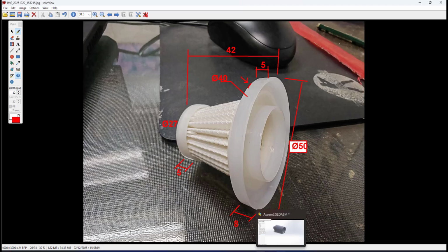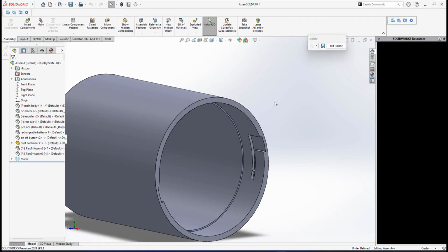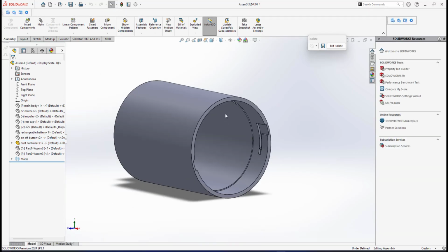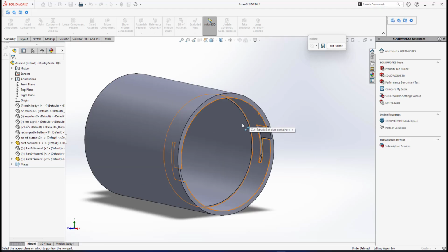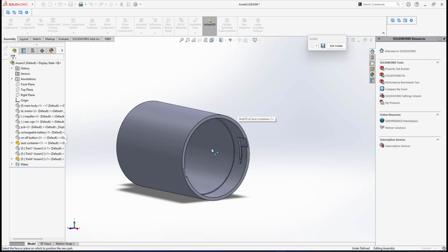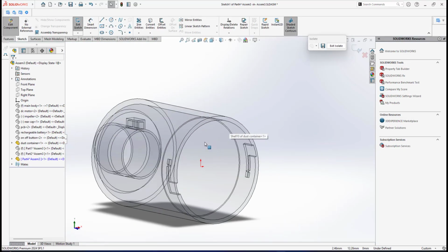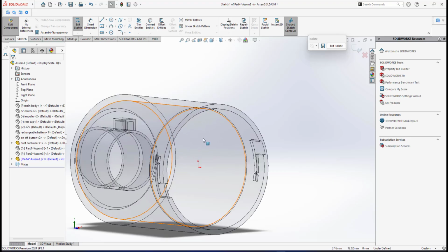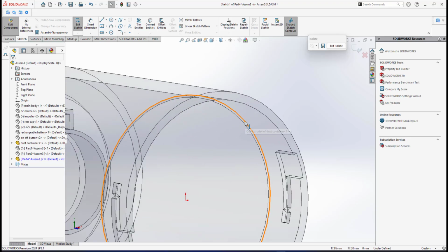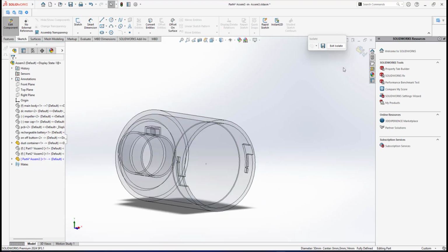Alright, so in SolidWorks, when I want to do a new part modeling in assembly mode, under insert component I can go for new part, and SolidWorks will ask which sketch plane I will start my new part modeling on. So I will select this surface as my starting plane. The cylindrical container turns transparent. Now I have the outline, so this will be my guide curve for my part modeling. I will convert entities, then exit the sketch and edit part mode.